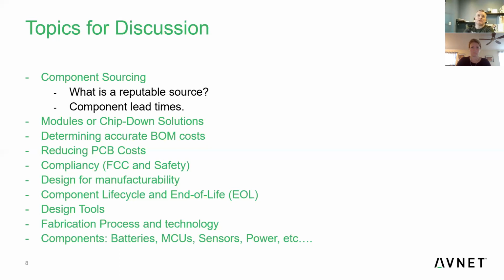There's a couple of what I would call small distributors for batteries here in North America. You're welcome to use those to source some, but you're going to find that the cost is high. With lithium ion and lithium polymer, you're forced to pick some type of Asian source. And in doing that, what I'd recommend, prior to going into production, is either yourself or have a company represent you go in and audit that company and make sure that it's actually reputable. I know it's not nice, it's not clean, but that's typically what I see happen: you're forced down that path.